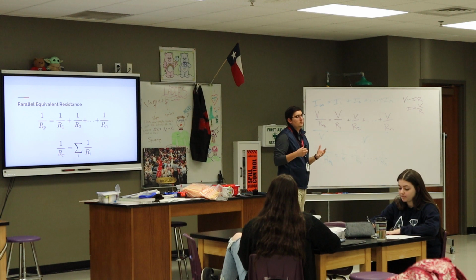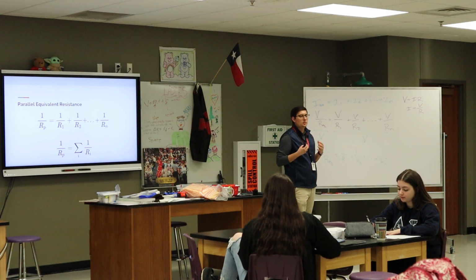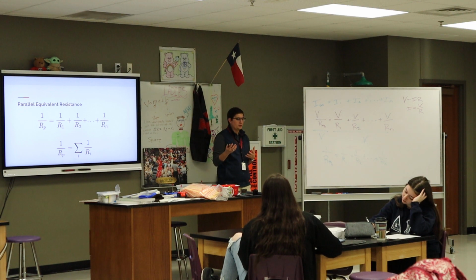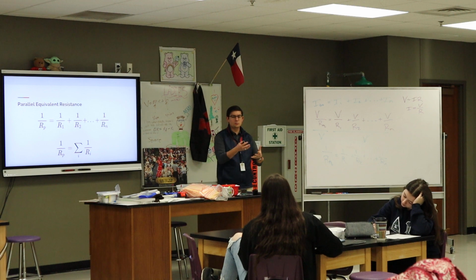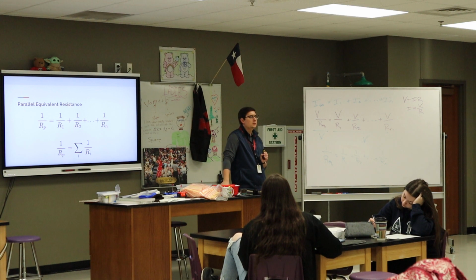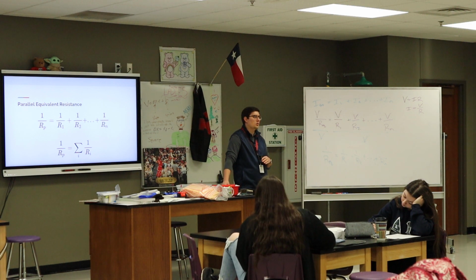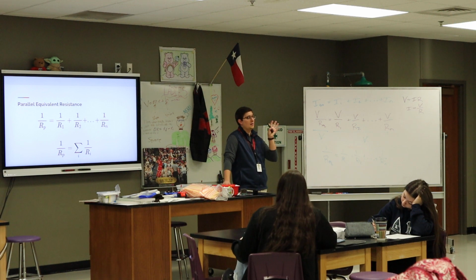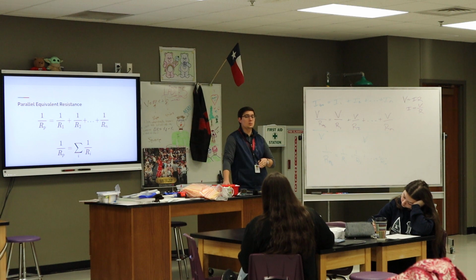So the real sticky part of solving circuits comes down to figuring out what information you have and then how you get the rest. My advice is to always, if you can, determine what you know about the circuit as a whole first. So determine the voltage of the entire circuit first, and figure out the current of the entire circuit first, figure out the resistance of the entire circuit first, because then it's easier to take that big idea and talk about all the individual elements.